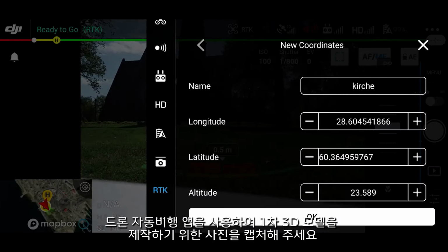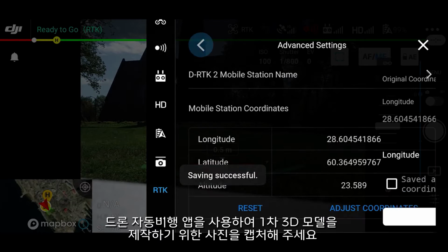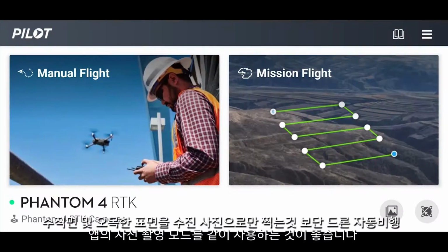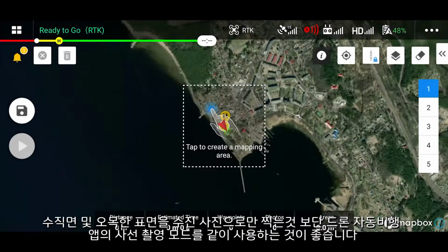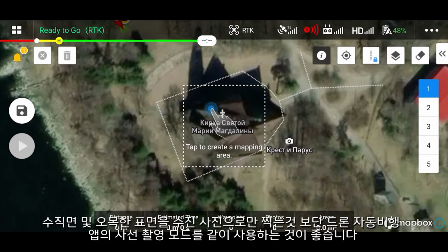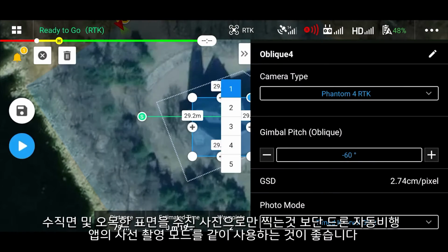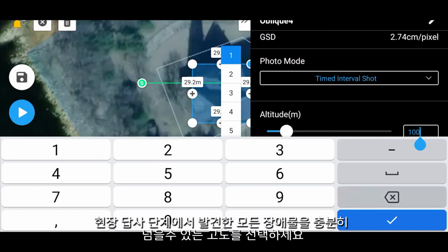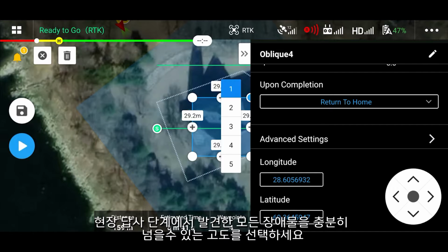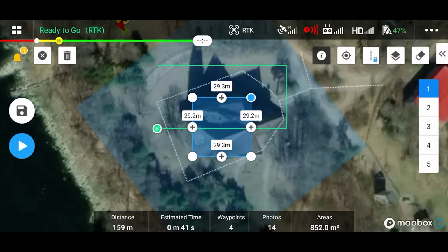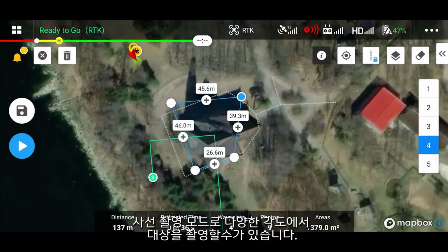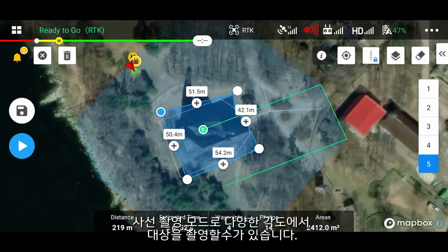Use the drone app to create an overhead flight plan and launch the mission to capture images for rough geometry reconstruction. To capture vertical and concave surfaces, you'd better use an oblique photogrammetry survey preset in your drone app instead of taking only nadir photos. Select sufficient altitude to avoid all obstacles you've noticed during the site inspection step. The oblique preset generates extra missions to capture the object under varying angles in addition to the regular nadir mission.